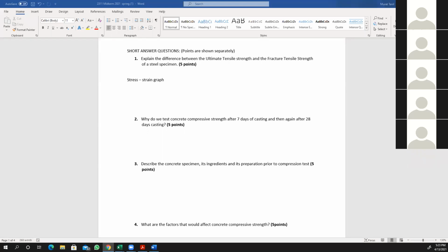Let me pull up what the perfect temperature is. It is advised that the concrete be cured at a moderate temperature between 50 Fahrenheit and 90 Fahrenheit. So in the temperature room or the humidity room, you keep the temperature between 50 and 90 Fahrenheit. And I mentioned before, a couple of years ago when we had freezing temperatures in New Orleans, we used to wrap the concrete with a tarp, with plastic, to keep the temperature higher than the outside temperature, just for the curing conditions.